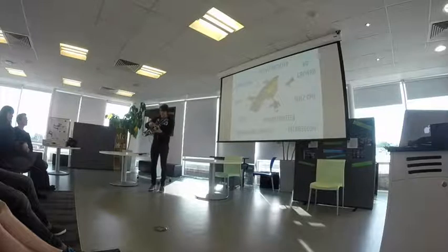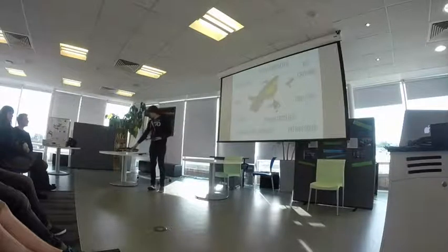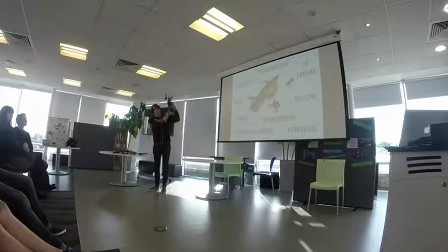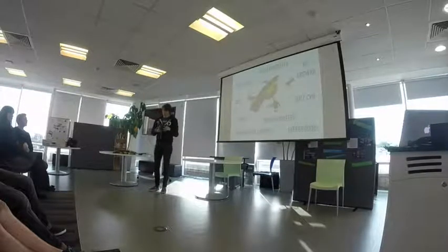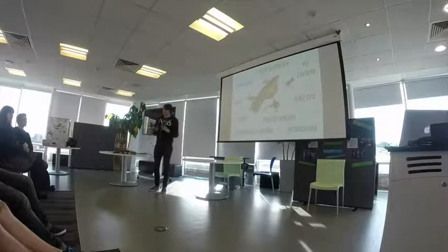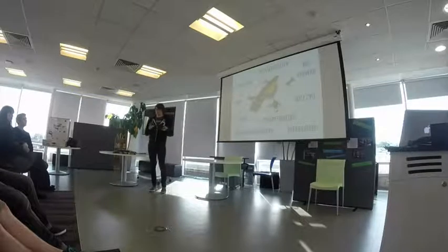We've got a protective polystyrene layer over the top to absorb any energy if you crash it. Then 4 motors and blades, an HD camera on the front, a low resolution camera on the bottom for doing optical flow, which is similar to a laser mouse. Ultrasound sensors, and internally accelerometers and a digital compass to work out which way it's facing. And it also runs Linux. It's a BusyBox Linux version running internally.